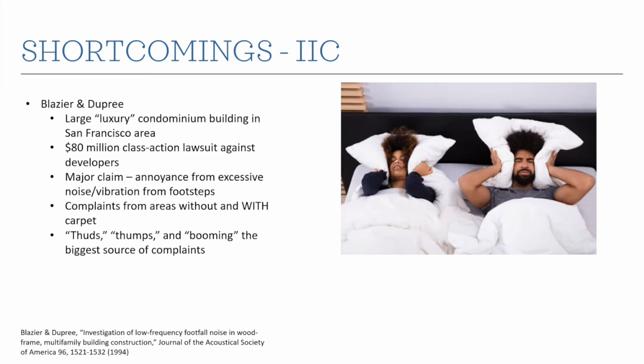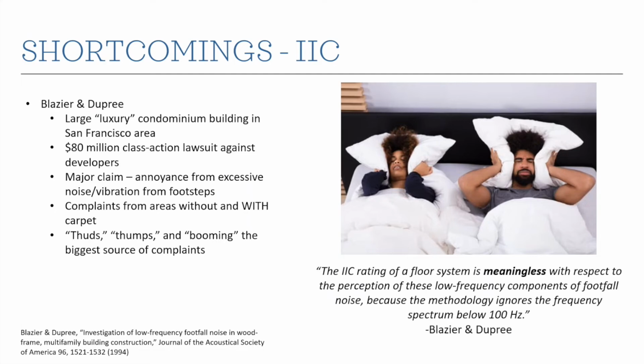And the reason for the complaints was primarily thuds, thumps, and booming. So the low frequency stuff. And sometimes the carpet doesn't always help on that, or it doesn't make it good enough, right? And here's a great quote from this: the IIC rating of a floor system is meaningless with respect to the perception of these low frequency components, the thumps and thuds of footfall noise, because the methodology ignores the frequency spectrum below 100 hertz.